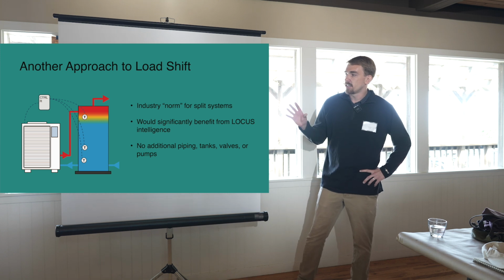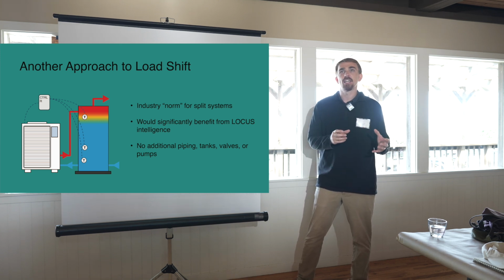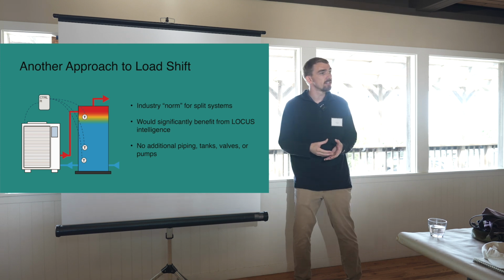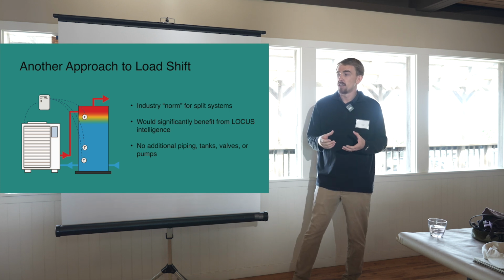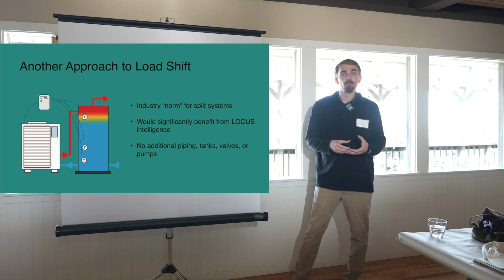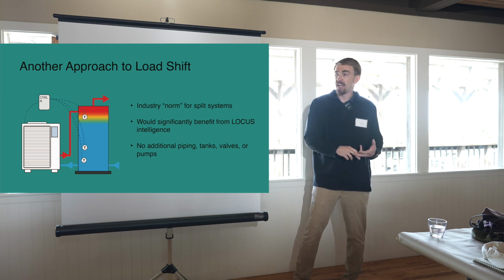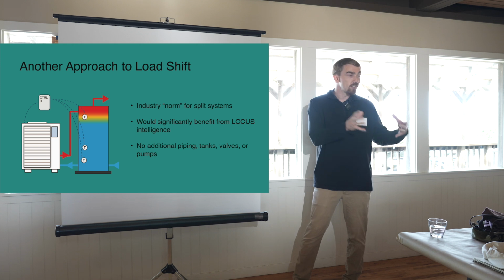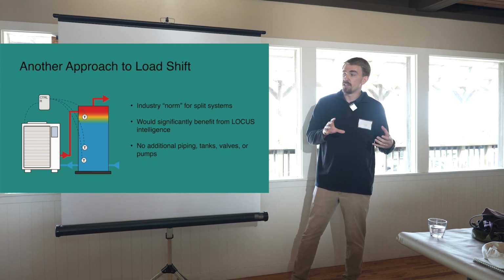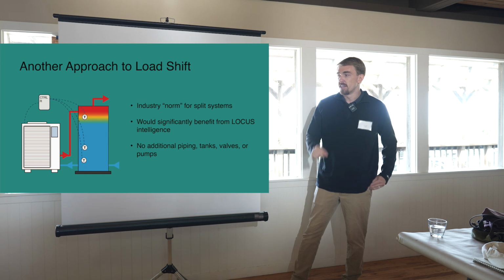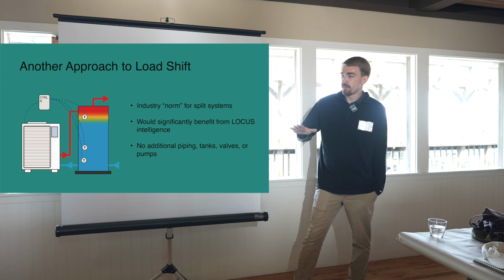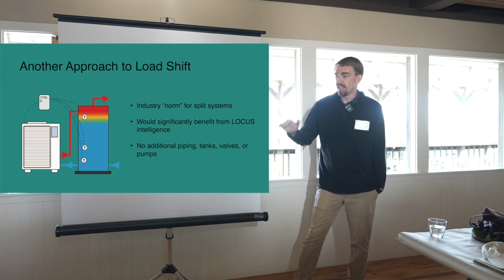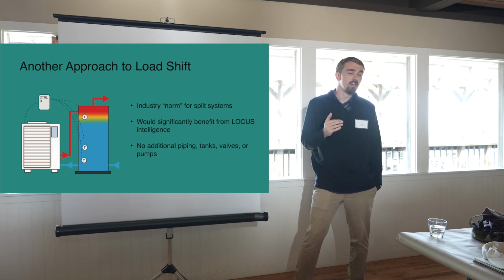And so that's one approach to load shift, which is really accessible for both residential and commercial buildings, and both integrated and split system heat pumps. So in parallel with this project, there are a lot of projects that are moving forward with load shift using a different control strategy, and that's really tuned into split system heat pumps or monoblocks with separate storage and large commercial buildings. A few different manufacturers have implemented this other load shift strategy where we'll have 3 different sensors in the tank, and the heat pump's going to look at a different sensor depending on what it wants to satisfy.